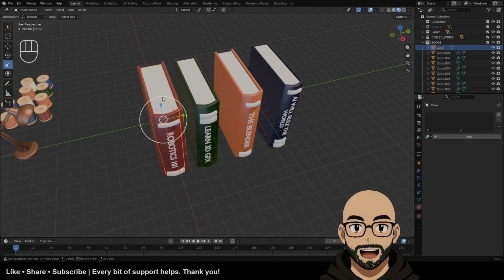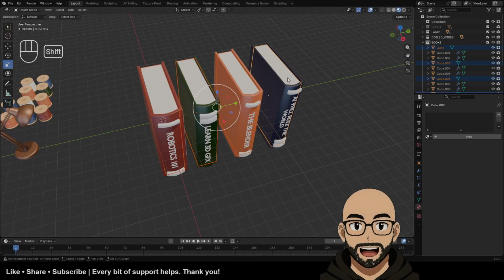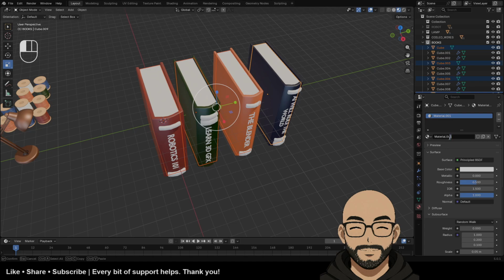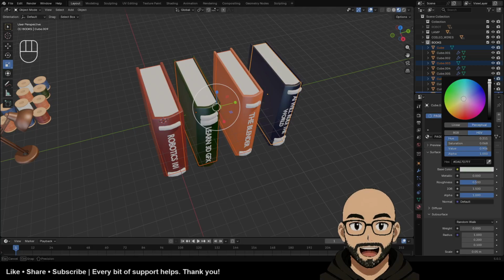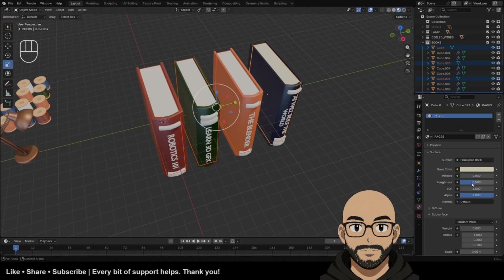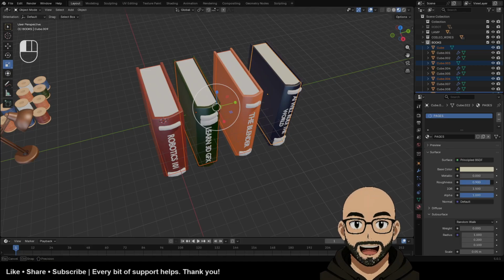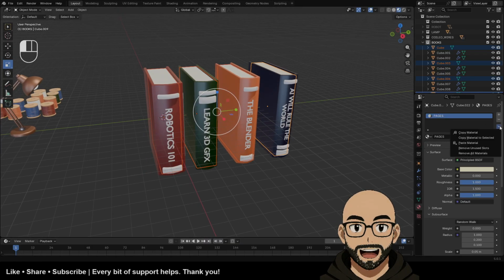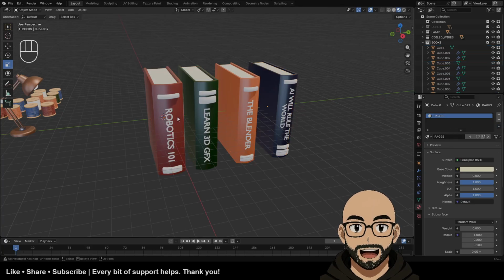These materials we want. I'm going to select all of these inside the pages. I'm going to just new, I'll call this pages, for example. I'll just give it a little tint. The roughness, we don't want it. Paper's not glossy, so I'm going to make it just 1. And then I'll just say copy material to selected.